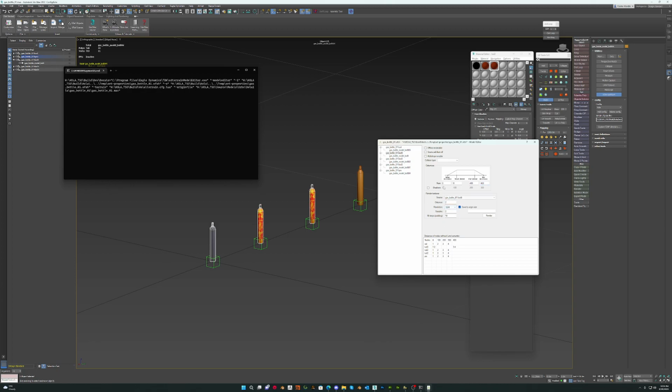Okay, so the near distance is 0, the near blend is 0. That means no matter how close you are to the model, it will always show you the model essentially. This far blend is saying the maximum distance this model will be seen at for LOD 0, remember we're on LOD 0, is 400 meters. So this is in meters.